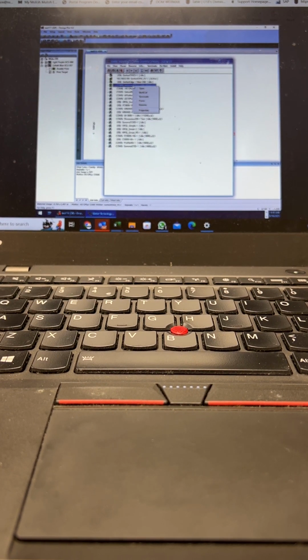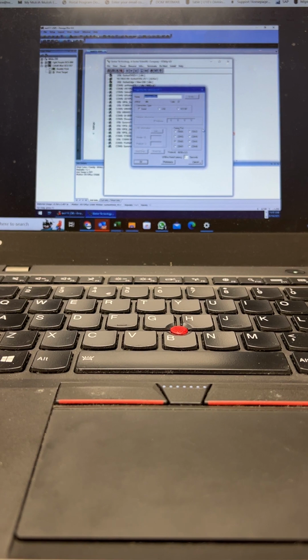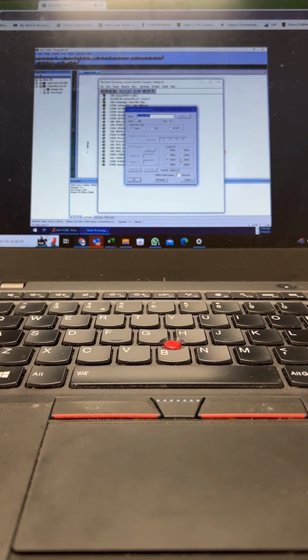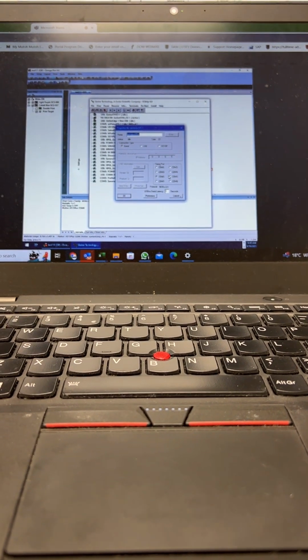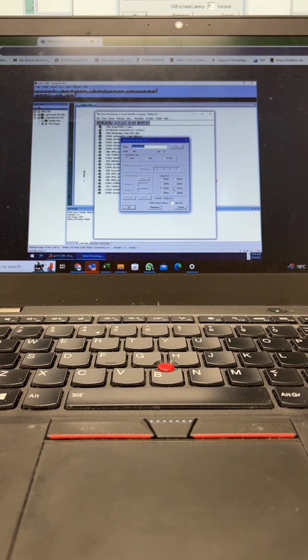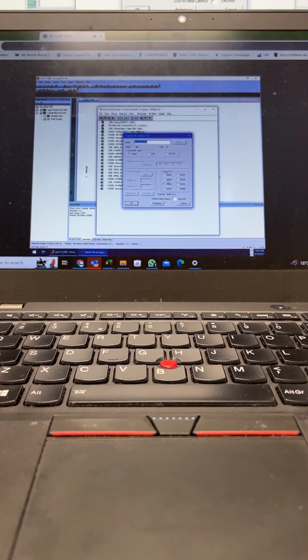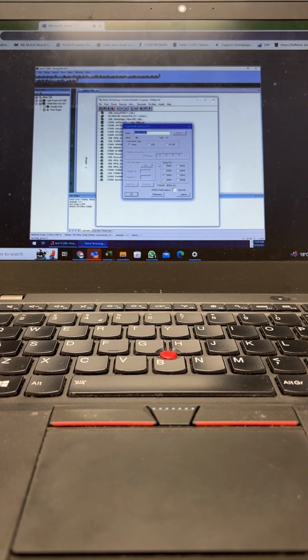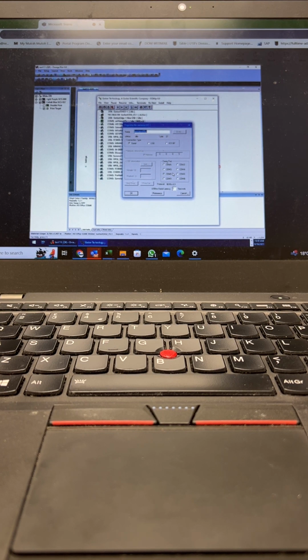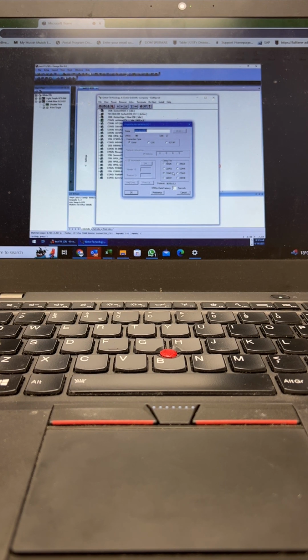For the plotters, when you go to Properties, this is where you could change the COM port that it's on. This is changing what the software is sending to, not what the USB to serial adapter is displayed as in Device Manager. So if you change it to COM 3 in Device Manager, you would need to come in and change the COM port in the Q Manager as well, or reinstall the plotter on the correct port.